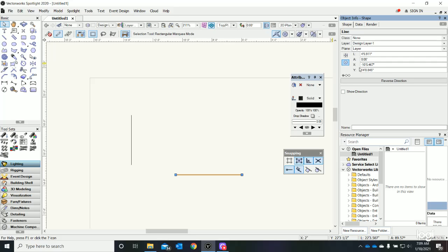Now, if we want to change the length of the line, right now this is at 4 feet 5.911 inches, which may not be the most useful dimension to a carpenter, right, or to someone that's hanging lights. And maybe we just arbitrarily drew it, and now we want to make it the exact correct size. I can change that dimension, and let's call it just 3 feet. Right? And if I change it to 3 feet, if you'll watch the line when I press enter, the line has now shrunk to where it's exactly 3 feet.